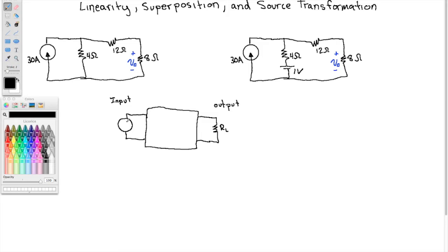So they're stored in memory, and then when you push play, those audio tracks feed into some circuit in the black box, and then its output terminals would be the headphone jack. And so what would RL be here? Well, that would be your headphones, and headphones can be very well approximated by a resistor, 20 ohms, 10 ohms, and so forth.